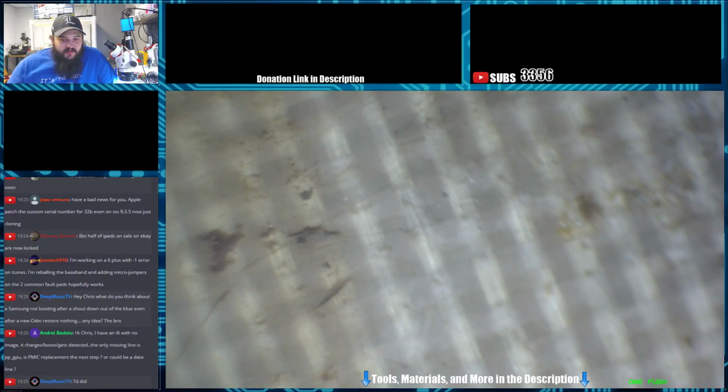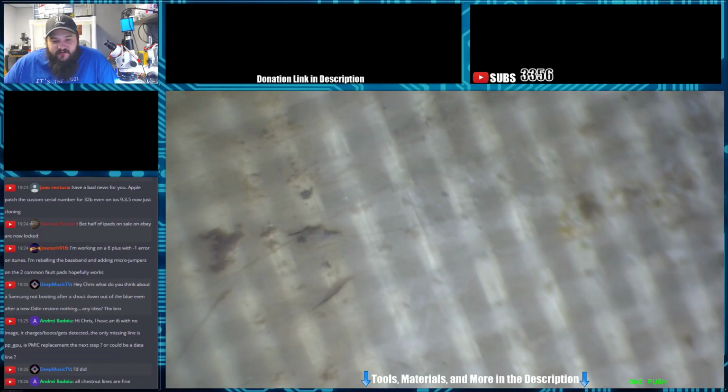I would check to make sure that your chestnut enable lines are there first. You got to think of it this way: if there's no enable signal coming from the LCD connector to tell chestnut to turn on, then GPU probably won't have any power. So I would think you probably need a chestnut enable line first, and then after chestnut is enabled, it probably talks to the GPU.